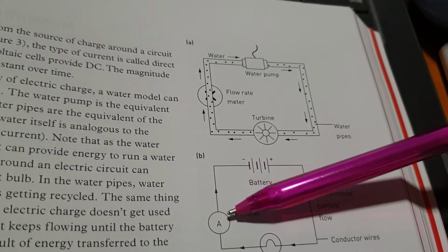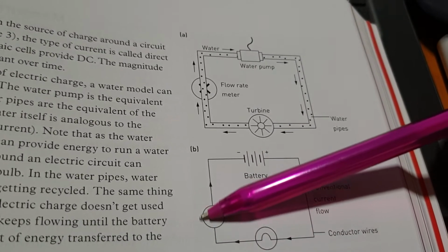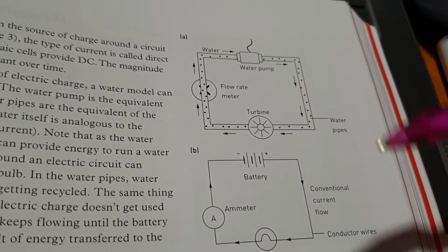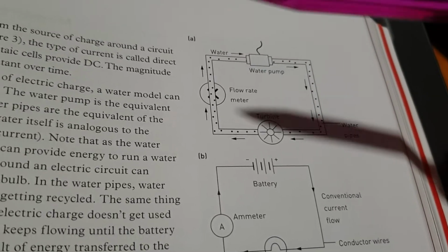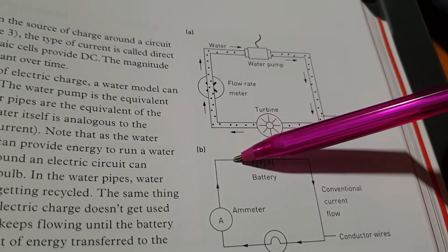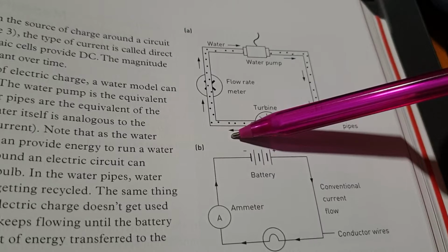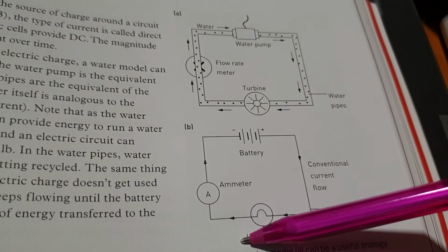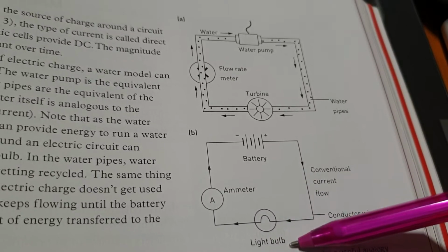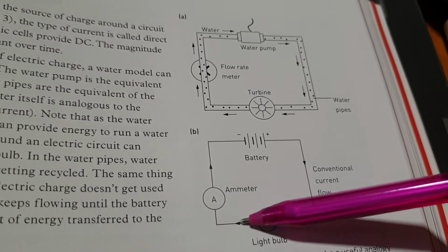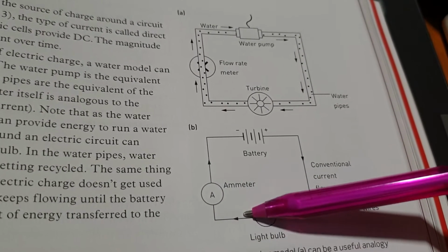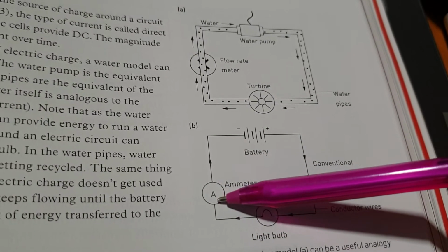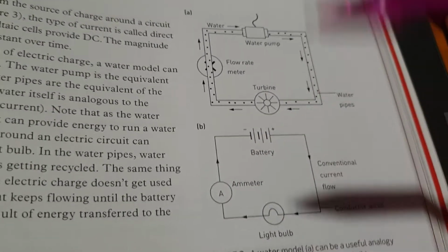That's the ammeter. So ammeters get joined into the circuit where you want to measure the current. We'll get on to voltmeters later on. They're joined across. So you would join a voltmeter up, over and down, or if it was here like this, across the circuit element that you're trying to measure. But an ammeter goes in the circuit.